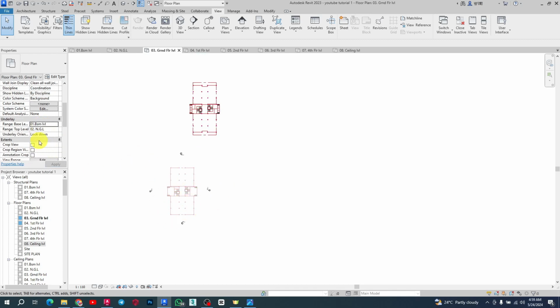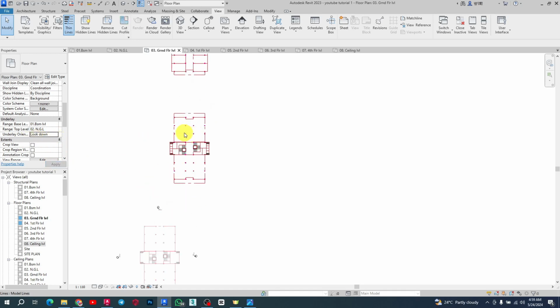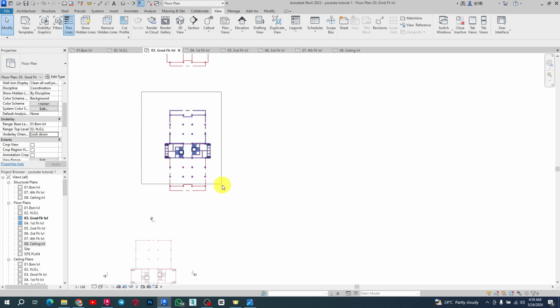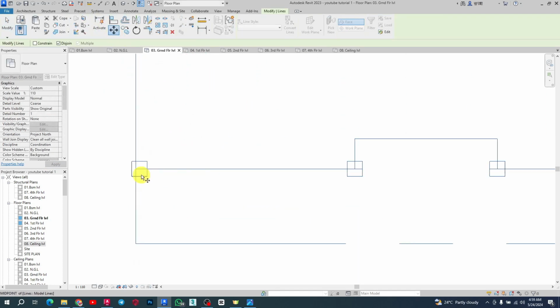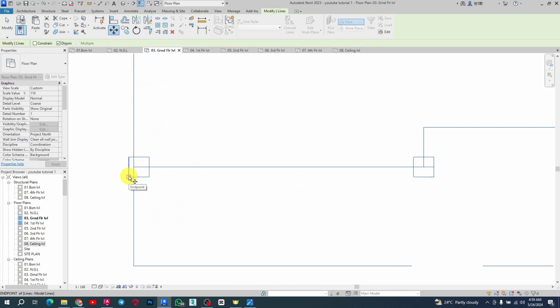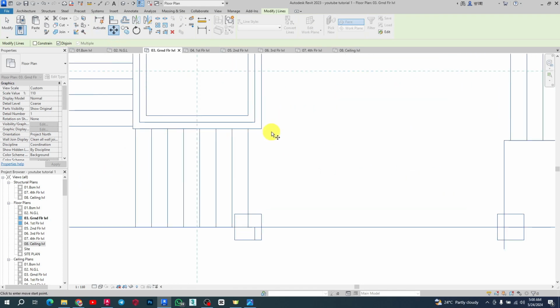And then something to always check here is that you see it's showing look down. Be very careful here to know what you're going for, right? By default it's always look down, so you're making it look down to that other level. So I'm going to copy our first floor. I'm selecting all of this, then I copy from a particular point, probably this position of the column, or I copy from my shared wall.